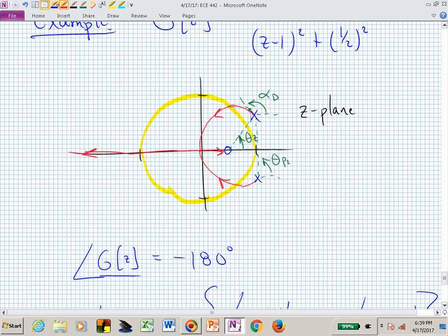How could we find this triangle location? Could we? Law of cosines. Because we know the radius, we can find the distance from that zero to the pole and find its magnitude. If we called this point P1 and this point Z, and this, let's say, is R, we know that Z plus R is equal to P1 vectorially. So that now R is just P1 minus Z. And if we wanted to know the magnitude of R, we could just find the magnitude of that complex number. And we know P1 was at 1 plus j 1/2. Z was 1/2.